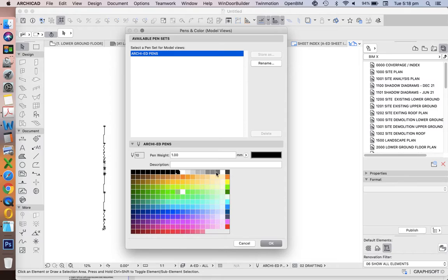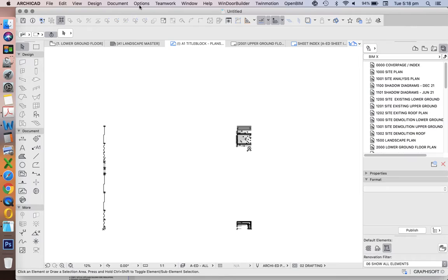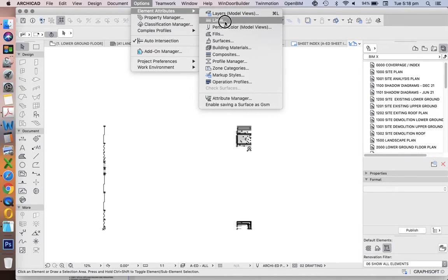Sometimes I'd use grey lines, and sometimes I'll be using fills, and I'll want those fills or maybe some specialty lines like 240, which is mostly intended as an electrical. So my lighting and electrical elements will go on this pen, meaning that it's red. And of course, this can then be output as red or changed to black with all pens to black if that's necessary. But otherwise, they're all on the same pen set.